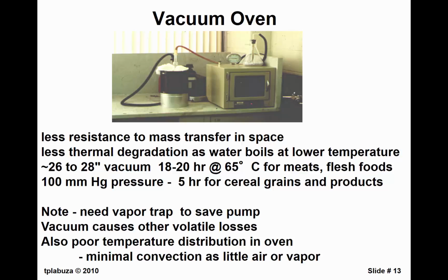Very importantly, the water is coming out, it's going to a vacuum pump. What you want to have before the vacuum pump is a cooling chamber where you condense out the water into the trap. We call it a trap. Why would we do that?